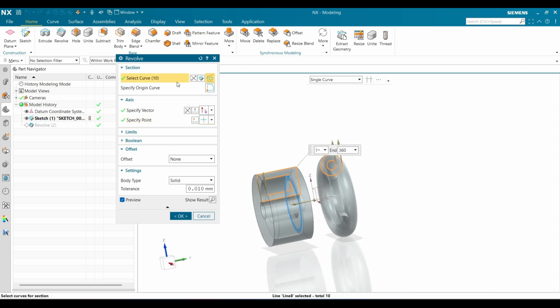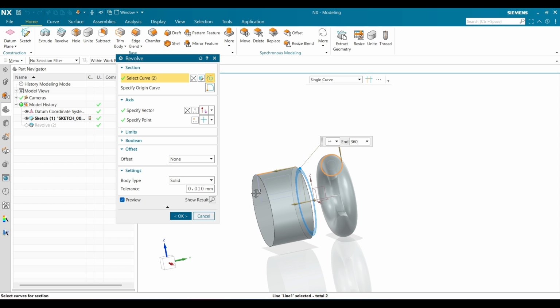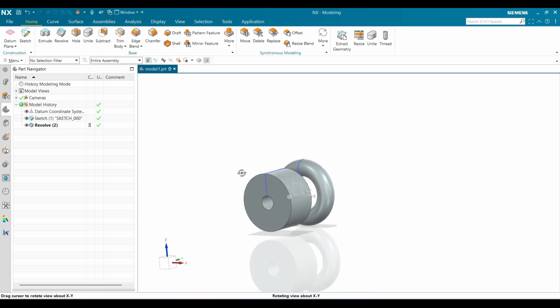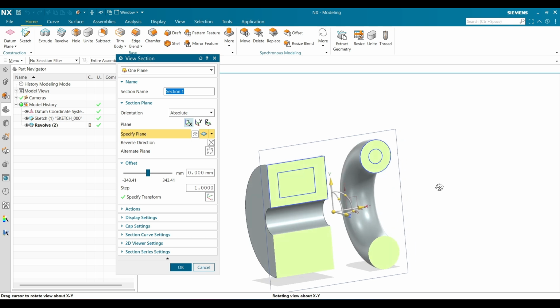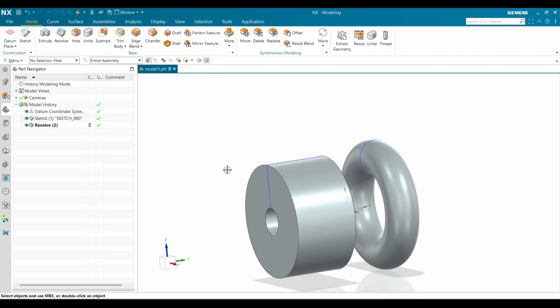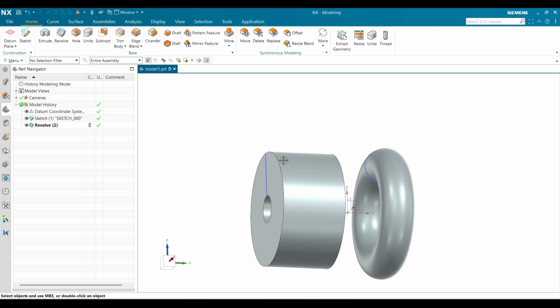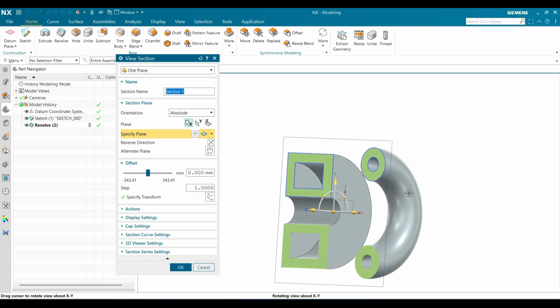Let's understand this command more with other shapes. If we select closed curves, then in their section view, we will observe that the revolved model will be completely solid. What if we select both curves, one inscribed in the other? It will create a hollow or subtract the material from inside it. Understand with this illustrated example. The shortcut key for view section is Ctrl+H.